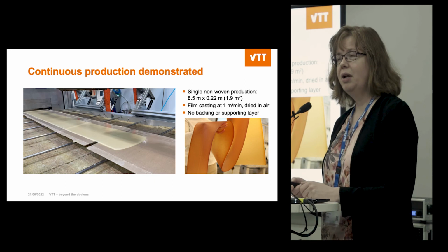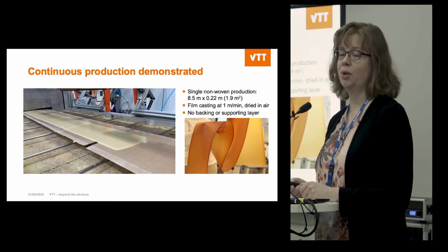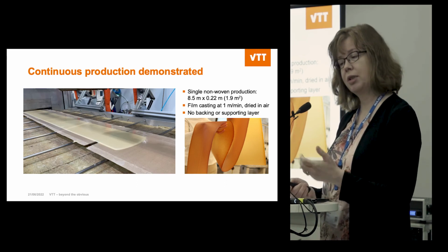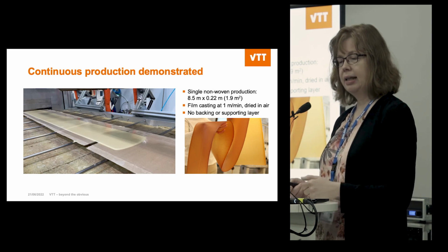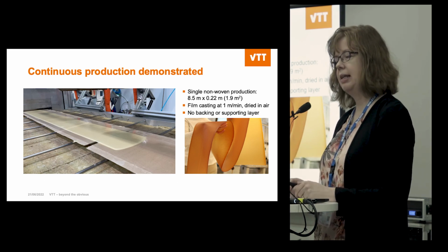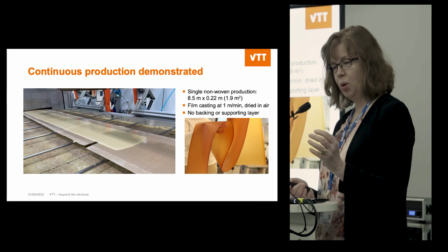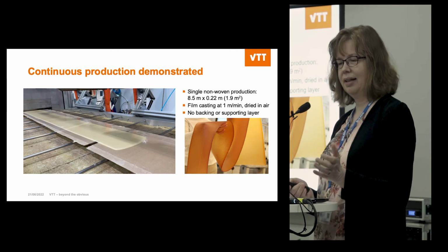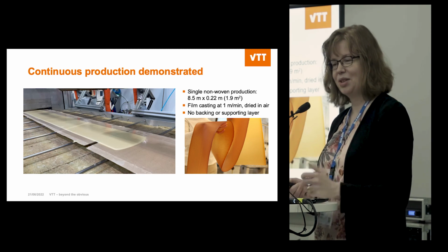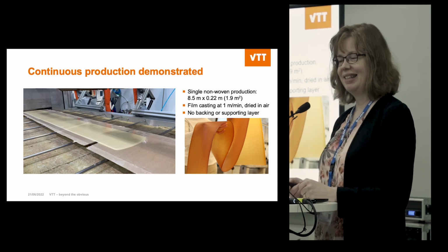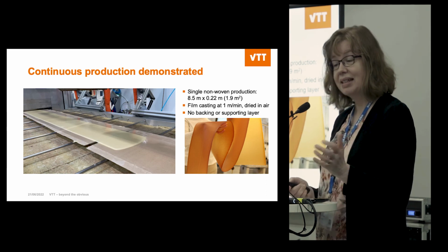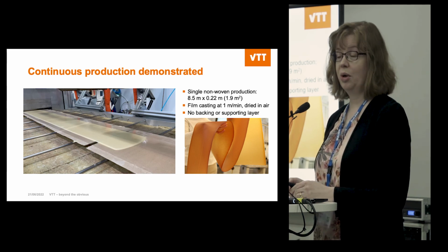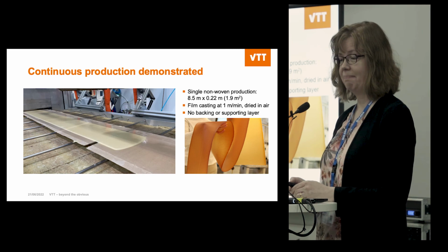One of the main milestones of this project was to demonstrate the continuous production of mycelium material, this non-woven type of fabric. And in this video, you can see how we pour the mycelium suspension on a belt, and then it is just running 1 meter per minute, and then it is ready. We were able to make even an 8.5 meter long material piece.